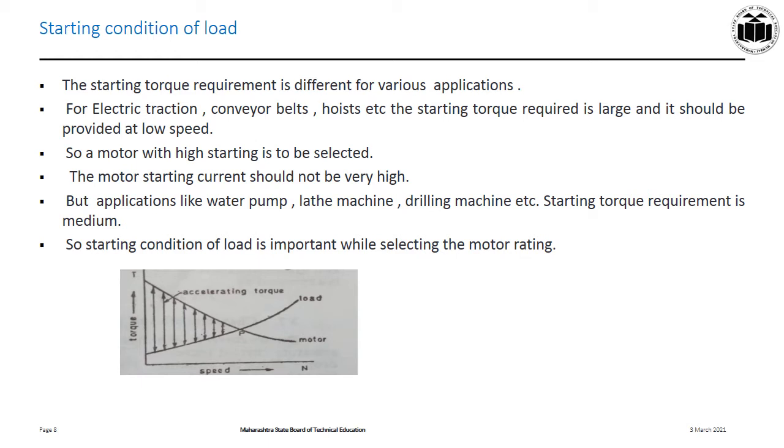On the other hand, if we see water pump, lathe machine, drilling machine, etc., starting torque requirement is medium. So, while deciding the size of motor, accelerating and the braking torque also have to be considered along with the full load torque requirement.